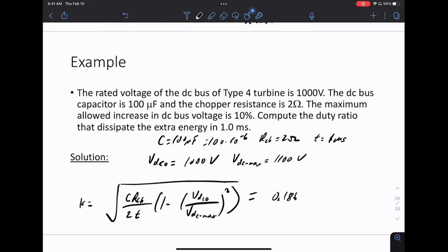Right, that's a good question. There are 2 factors it comes from. One, there is a max of the max. Then there is the voltage right now during this transient. The first one is the maximum allowed voltage I allow the transient to take, let's say it's 20%. If it's larger than that, I'll open the breaker in the system. If it's under that, the breaker wouldn't open, but the voltage will get passed through to this DC link. So let's say the amount that gets passed through is 10%. Then we'll change this to control that energy.